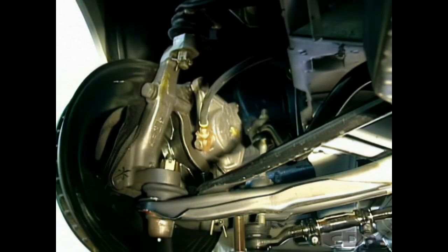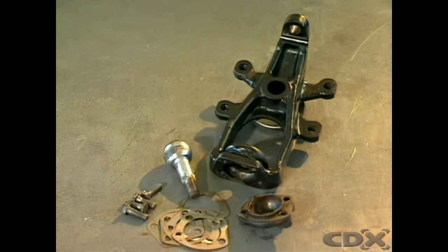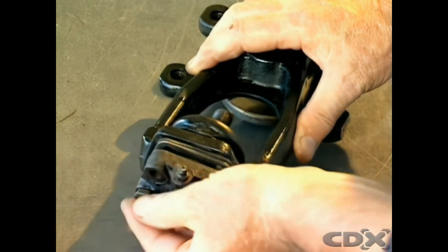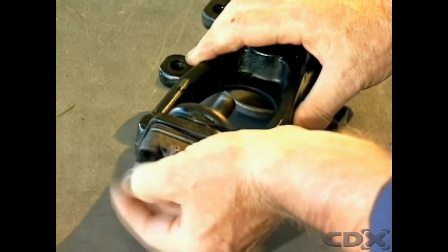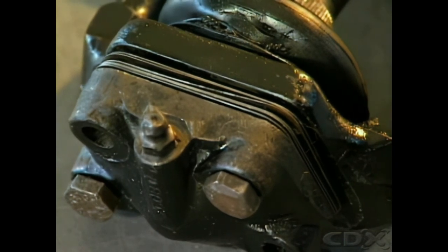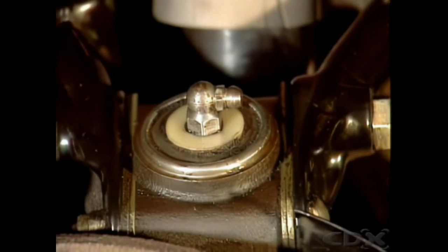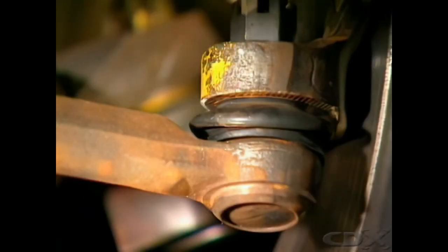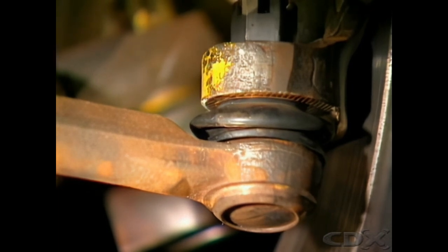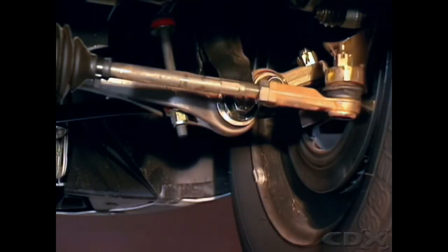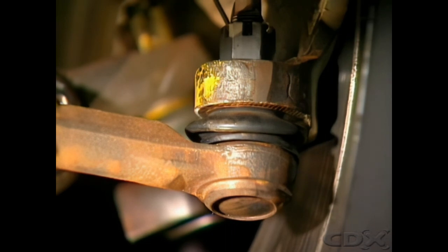A taper on the stud locates in a mating taper on the suspension unit, and a rubber seal keeps out dirt and water. Some ball joints can be dismantled to replace the seats and ball stud and allow for adjustments. Shims between the upper and lower halves of the joint allow free play to be controlled. Grease nipples can allow for periodic lubrication, but most joints today are sealed for life, and no regular maintenance is required. On tie rod ends, the ball joint is usually self-contained and attached to the tie rod by internal or external threads.